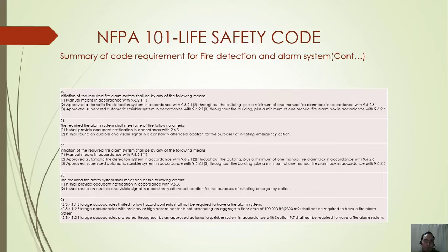Either the occupant notification is provided all throughout the building, or it will sound only audible and visual at first in a constantly attended location within the building. So it's the trained personnel who is going to raise the alarm in case of fire. Okay?